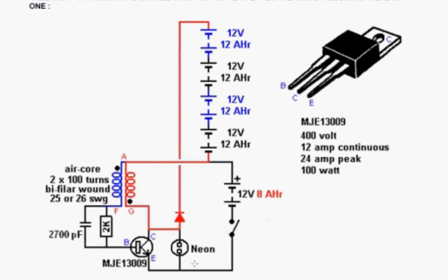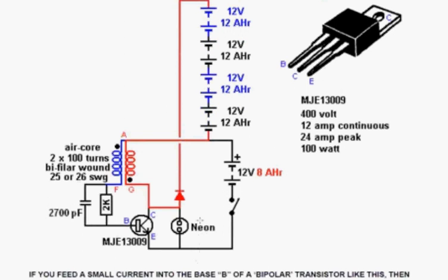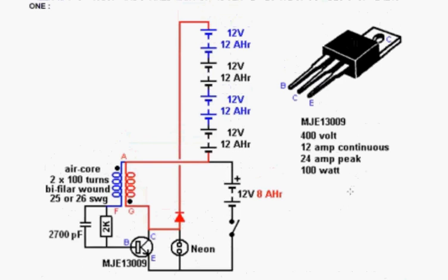And it has a neon, which is effectively a spark gap. This particular neon spark gap is typical. It's called a neon bulb, and it triggers somewhere between 90 volts and 110 volts. Now, the reason it's in this particular circuit is this particular circuit is sometimes referred to as a joule thief. But this is a very powerful joule thief. And the current fed in through the resistor to this transistor is quite large. And because of that, the wire on this coil is fairly strong.